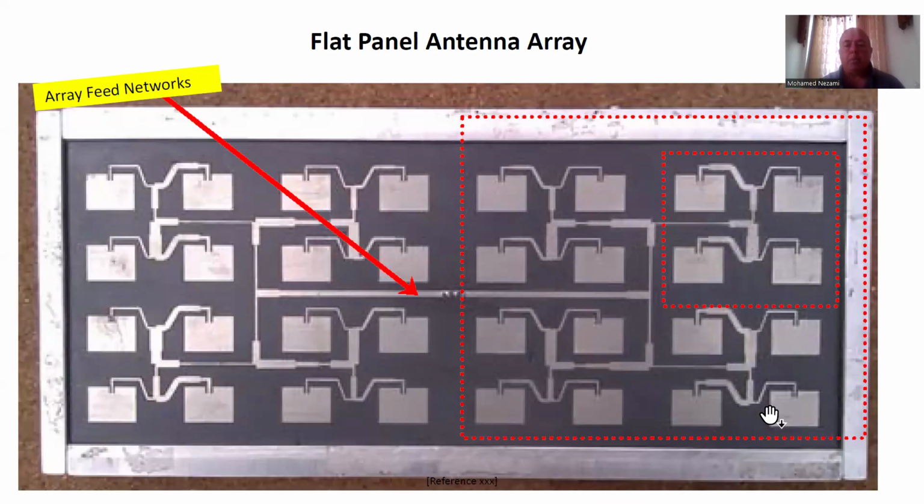Here's another example. The antenna array feed network is what you see here, what distributes the signal to all of these. And in most cases, it's really symmetrical. So you start out with a unit cell like this, where the amplitude distribution in here, as you can see, these impedances are different. So this is tapered excitation or illumination. You can design this here, and once you design it, all you're going to do is just copy it over and over and over.